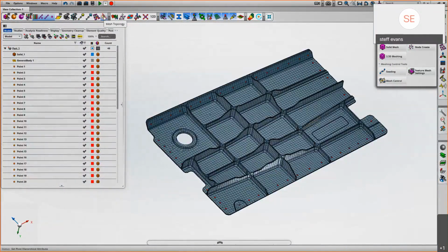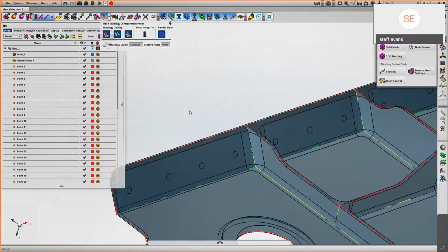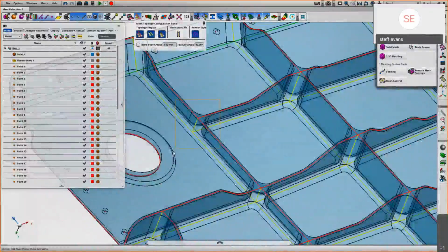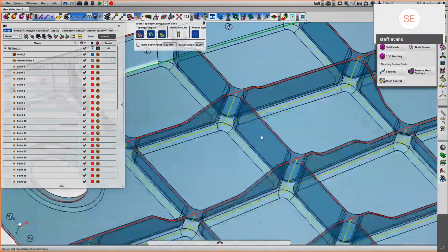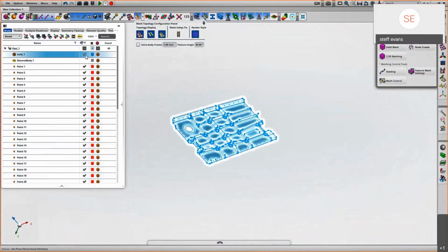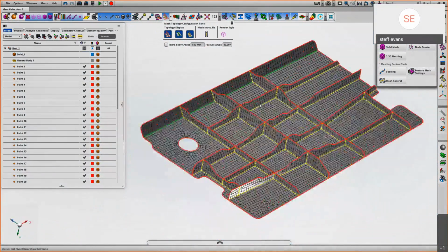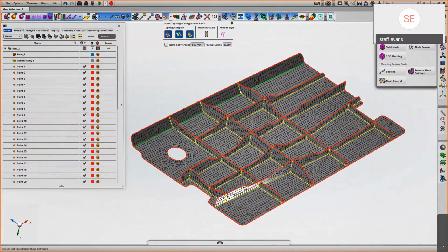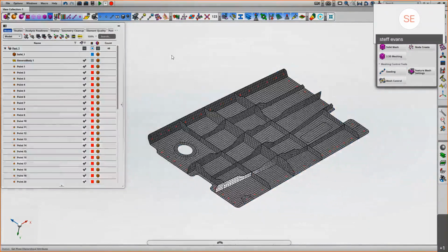Okay, we've got these mesh topology tools. Similar to how you would display the geometric line edges, so the red, yellow and green edges, depending whether it's a T-section, a free edge or a shared edge, we can do the same with mesh. So we've hidden the underlying surface geometry and we're showing the edges of the mesh and comparing that with the geometry. It's good practice to do this before you consider the next steps. We can show that with and without the mesh, so we can put it in transparent render to make the edge viewing more straightforward. So we can see all those nice connections in there, underpinned by the mid-surfacing, of course, but flowing through to the underlying mesh that we create.